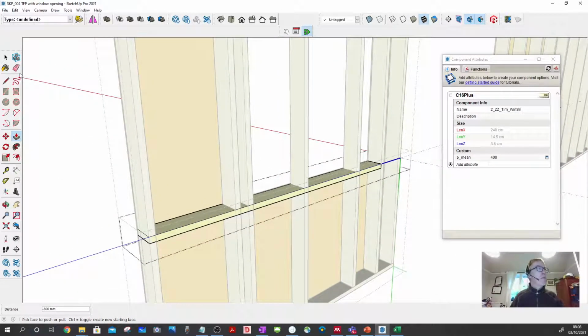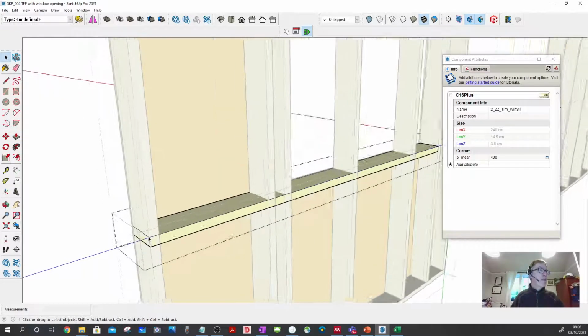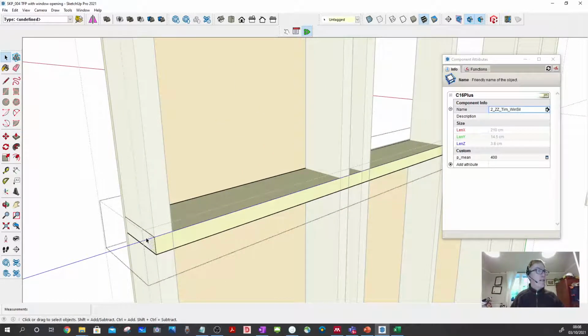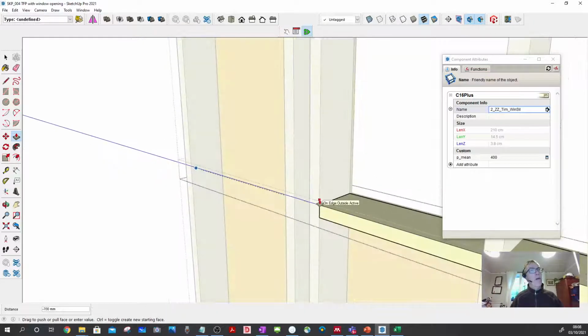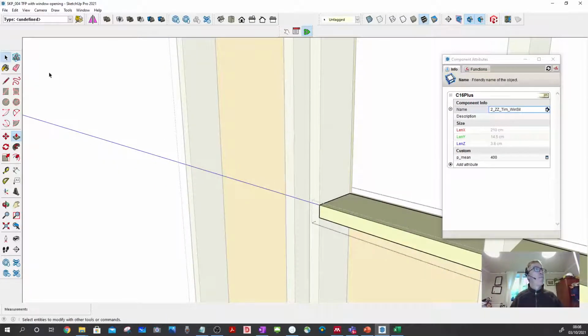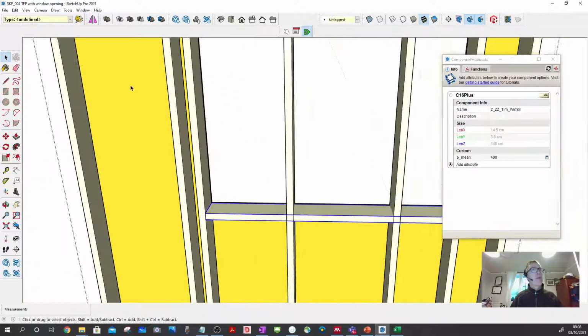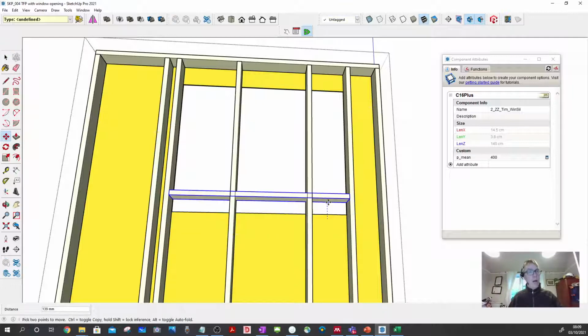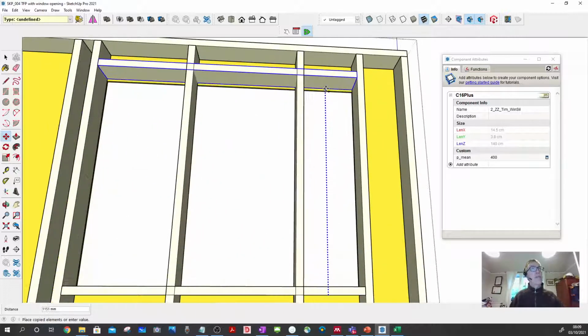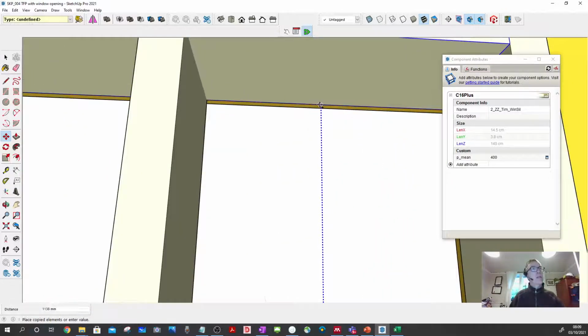To make it easy, we'll select the select tool, press that surface there, now use the push and pull tool and move that back until we are on this face here. We can come out and have a look. Okay, that's absolutely perfect. We'll now select this one more time, press move, press Control to keep the original, press up to lock it on the vertical axis only, and zoom in until it snaps on to that point where we want it.